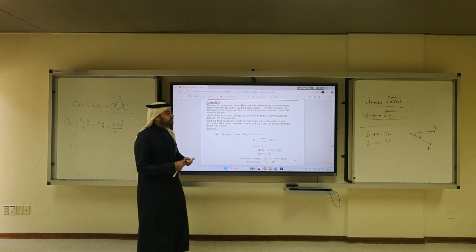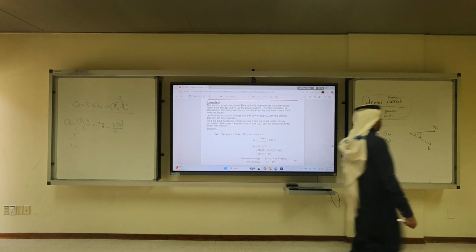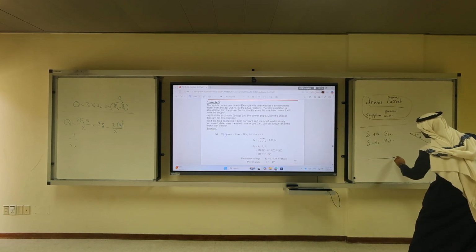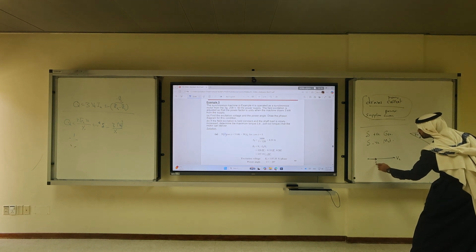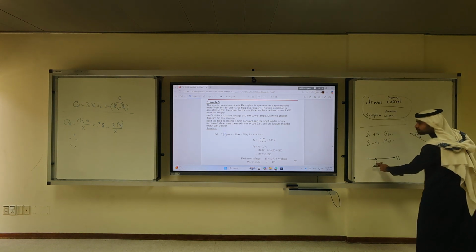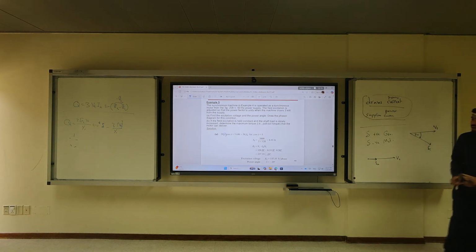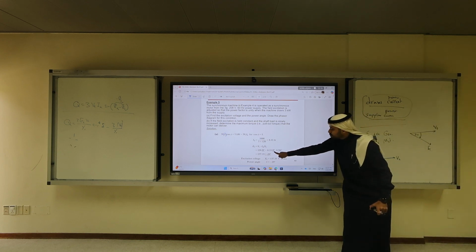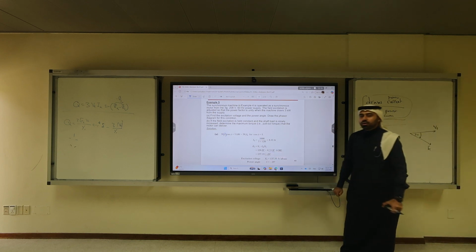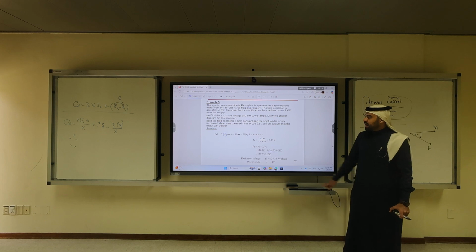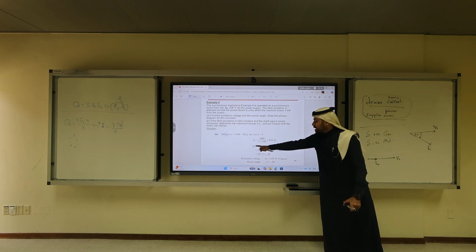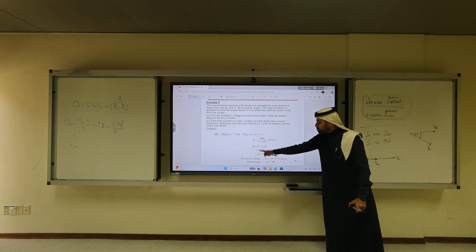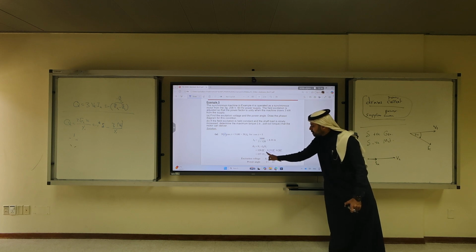If we operate at unity power factor, it means that VT is in phase with IA. So IA would have an angle of 0. That is why if we substitute IA, we put an angle of 0. And then you should get EF to have this magnitude and angle.